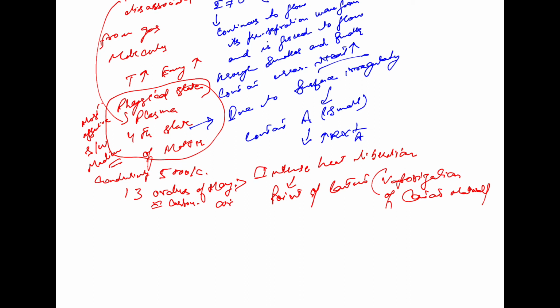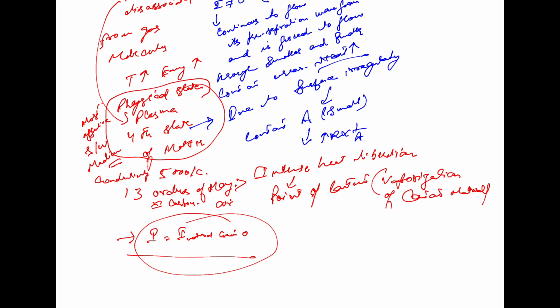Now, one more point: when the current passes through the natural current zero, it can no longer sustain the arc and hence the circuit is broken. So, irrespective of the point on the current wave at which the breaker attempts to interrupt, the current is always interrupted at the natural current zero.